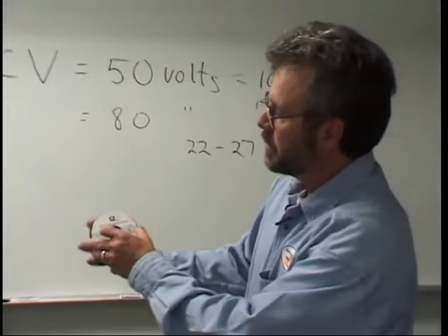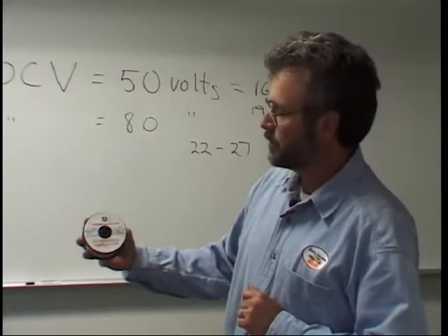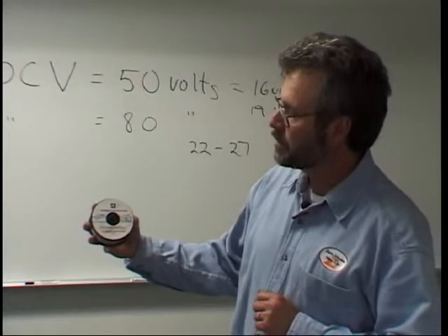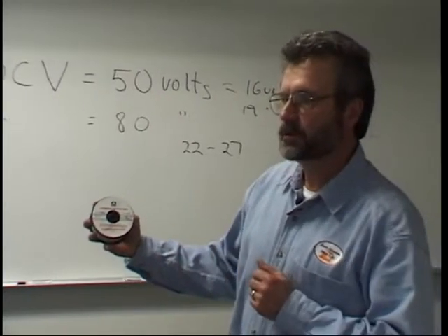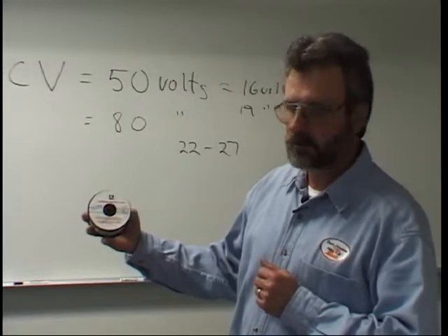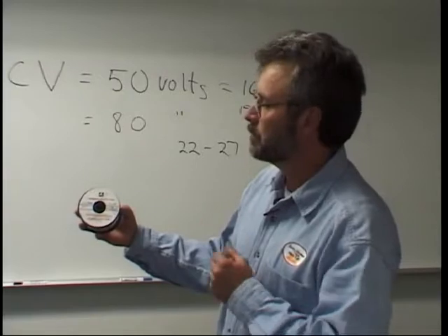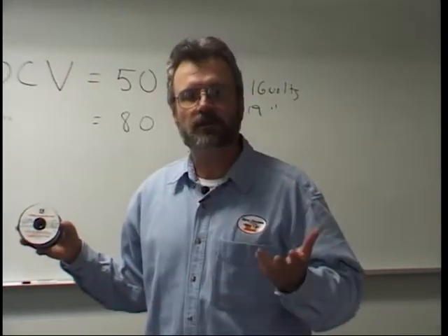They're in wide use, and this happens to be aluminum alloy 5356. For those of you that have studied Chapter 3, you'll see that this is one of the main aluminum welding alloys out there. And this has to be used with pure argon. When we weld with aluminum, we'll weld with pure argon. So I just wanted to show you what's underneath that cover when they show you a spool gun. So we've got three types.